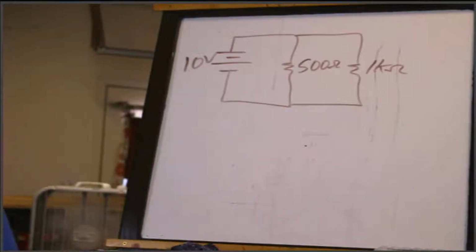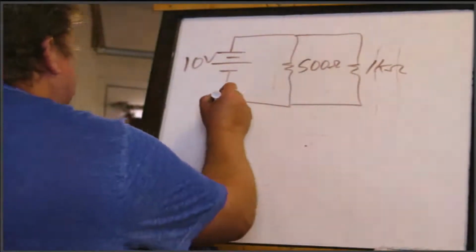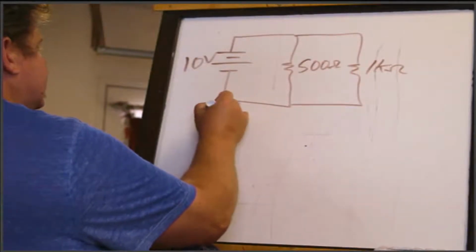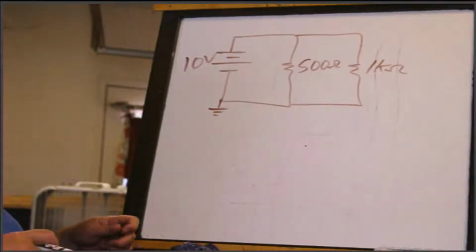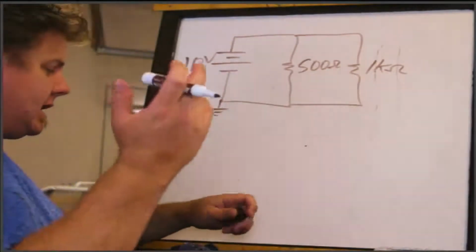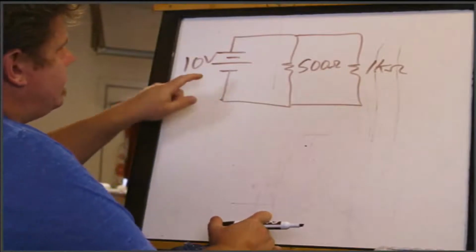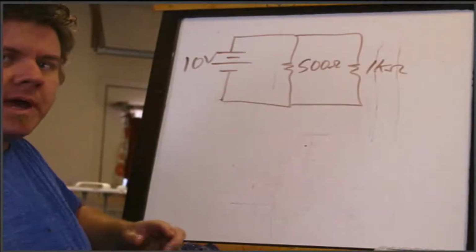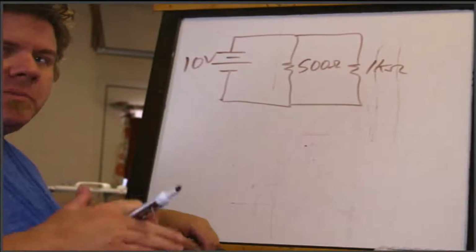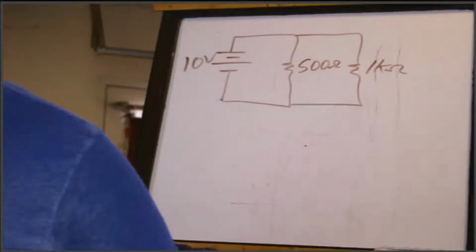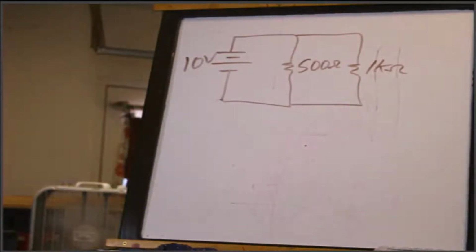And I'll restate this again. I don't draw the ground. Some professors you'll see do this, like some professors on YouTube, and if you have other professors, even at Ivy Tech or somewhere else that you go, they'll put the ground in here. It's always implied with me that it's on the negative terminal of the battery, unless I do differently. So that's my default. You'll see that in Multisim that's not good enough though, because they force you to put a ground in before it'll even run. Or it'll run and it'll give you wacky answers because it won't have a ground reference to measure everything against.